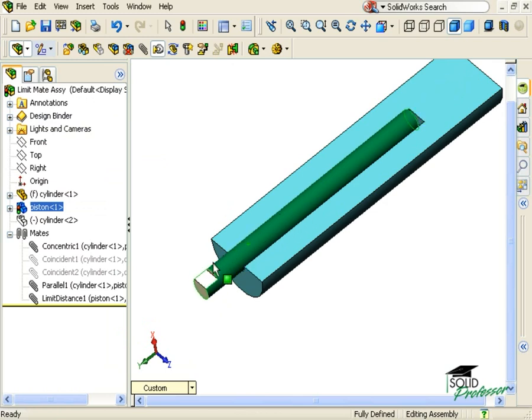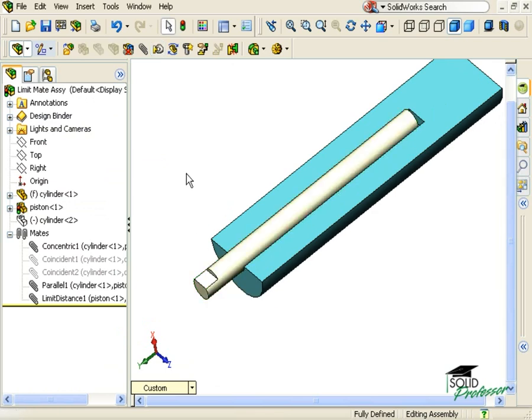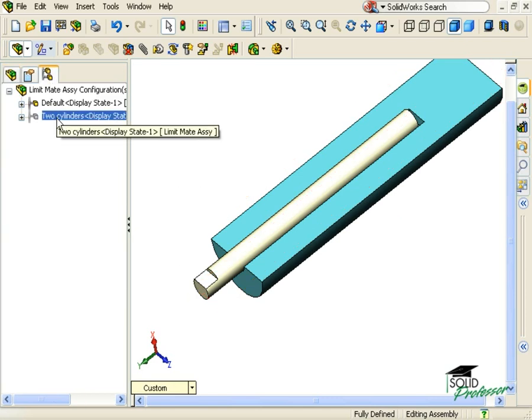The reason is that when 2 vertices are selected, instead of using distance values only in a single direction, the range will cover both possible solutions, 0 to 20 in one direction, as well as 0 to 20 in the opposite direction. This behavior only occurs when points or vertices are selected, so it's easy to avoid this by just selecting faces or planes.